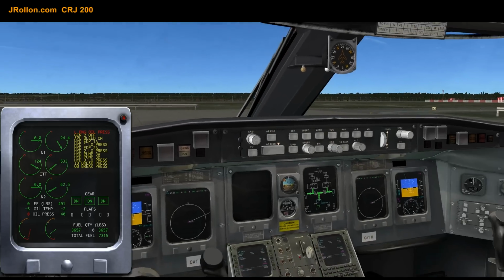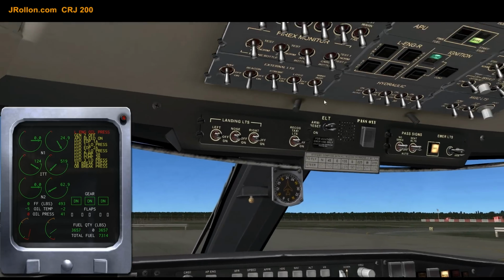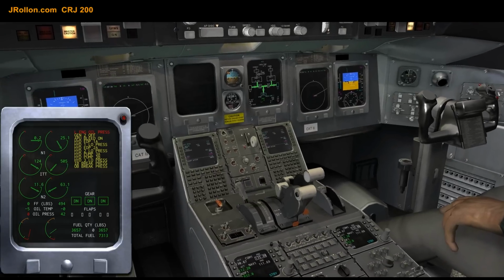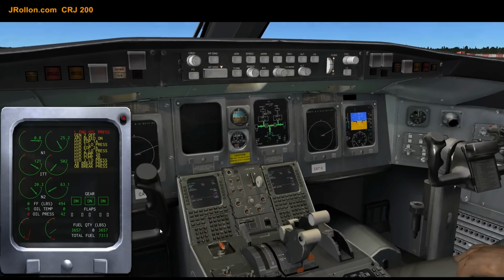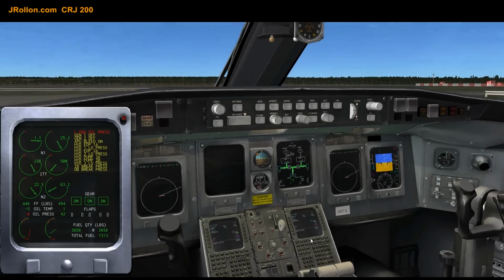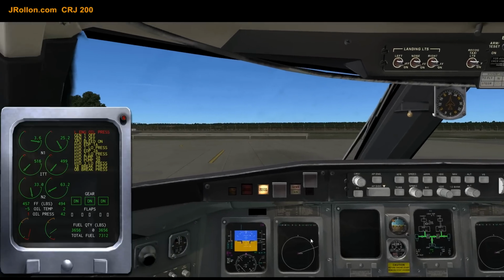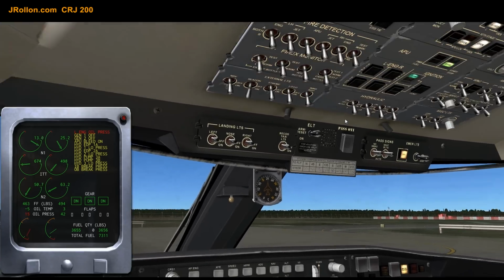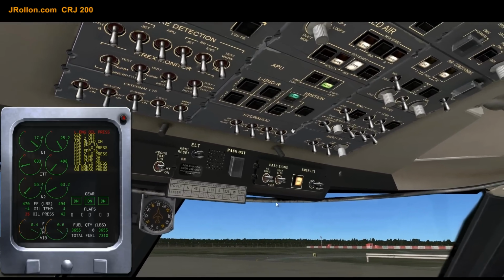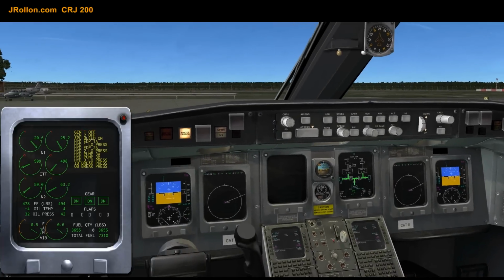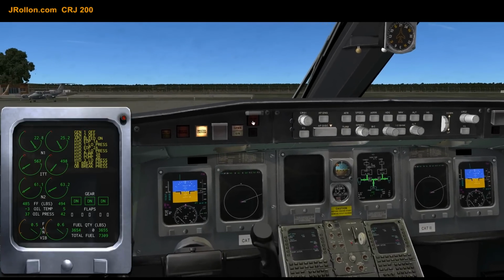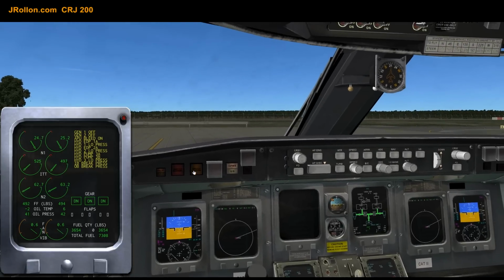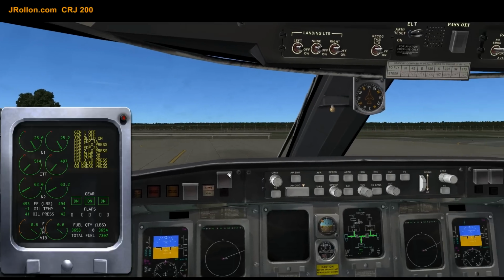Okay, and now we have to start the second one. You have to be very careful not to raise the red lever before it comes to 15, because if not you are going to have a hot start and you can burn the plane, and this is also simulated, so you have to be careful. If you do it sooner than that, you have to stop the process here with this button and then put the lever down before, because if not, you have to apply this one to switch off the engines, to burn off the engines.